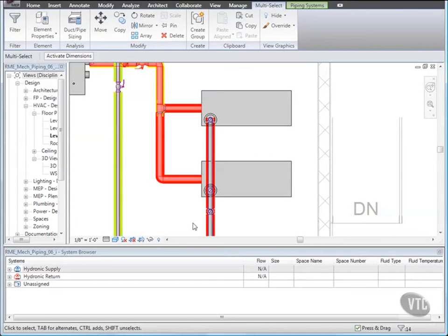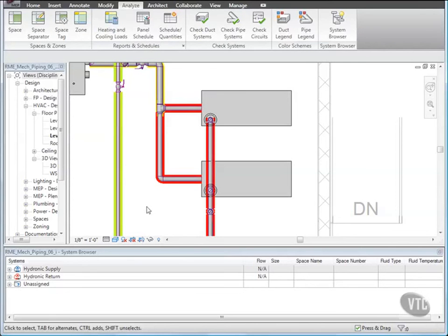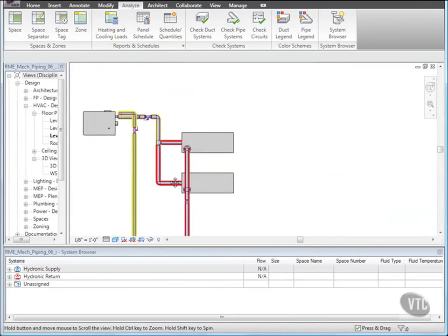Clear the selection and note here that errors may occur while you are attempting to create pipe geometry as a result of converting a layout or during sizing. The most common cause of these errors is that there is insufficient space to create the pipe, or offset elevations are incorrect. Either relocate the system components, or select a different layout solution, or manually modify the pipe. Remember to always check pipe connectivity after modification.